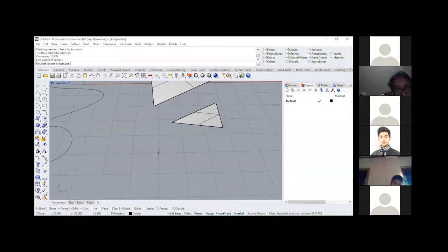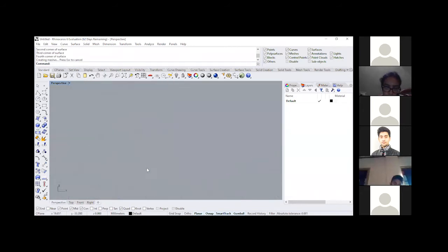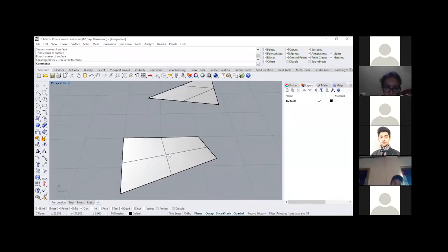Now you can see how if I start it over here and take it forward, it's snapping to the grid intersections, right? Now in between my command execution, I can even turn it off. And now you can see that it is not snapping to any of the grid intersections. So now I have more flexibility in terms of where I want the corner of the surface. So is that making sense? How grid snap on and off affects the modeling? I want you guys to try it out.